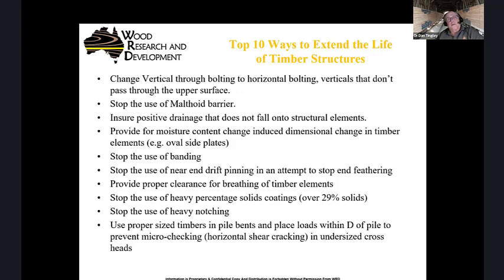Stop the use of near end drift pinning. Provide proper clearance and breathing for your timber elements. Stop the use of heavy percent solids. Don't put paint on things that are 29% solids or more. Stop the use of heavy notching. Use proper sized timbers for your piles or your caps.